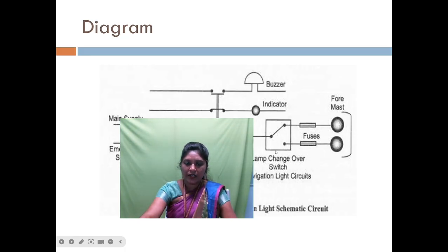During normal condition it takes supply from the main supply and the lamp will glow. In case of any failure, this relay will be de-energized. When any of the lights is defective, the relay coil should set the commands to the buzzer and the indicator system, so that the buzzer will make a sound and provide the warning.